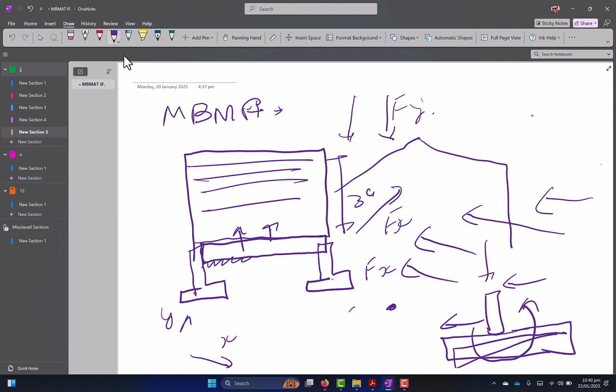Usually you have a spring support system here, so partial load is transferred through the deformation of this plinth beam, the remaining load is transferred to this beam, and beam action happens. Since in this load case there is no masonry, there is no need of a plinth beam, to be honest.